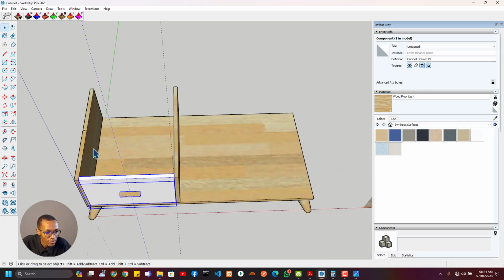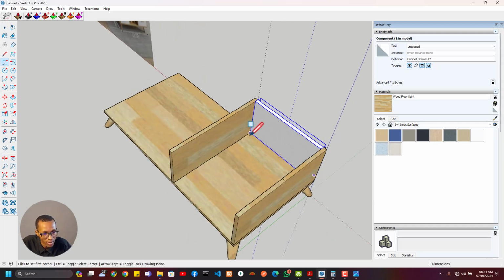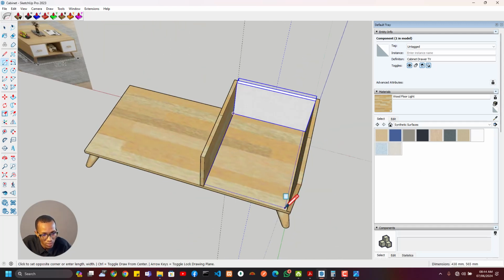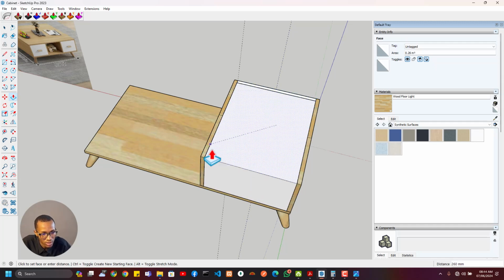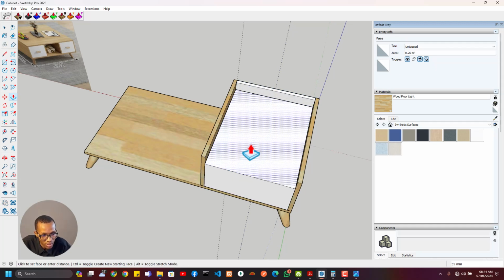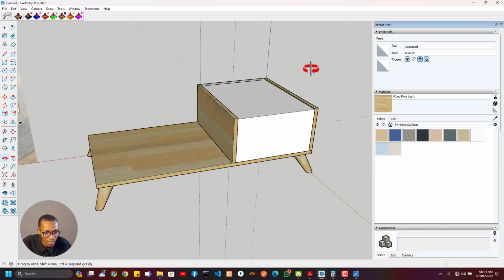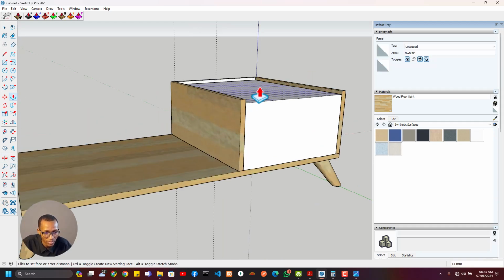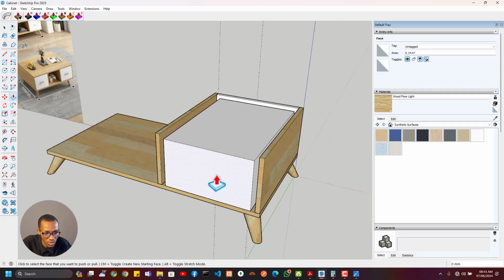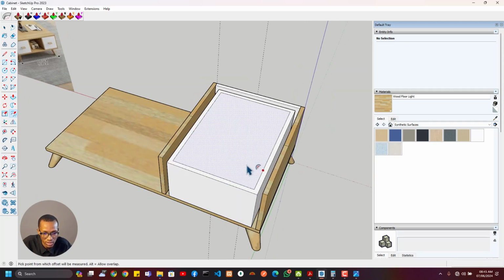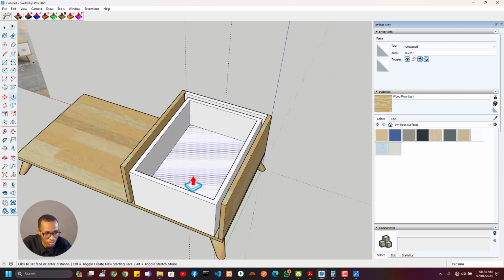All right, so from here I could just come and let me just draw a rectangle all the way. Then I'll pull this rectangle to the top, and I'll push it down by 10 or 20. Let me do 20. Push it out by 20. All right, then I'll do this by 20 as well, and then I'll pull this down, so the total thickness here is 240, so I'll do 220 so that I can have 20 thickness.